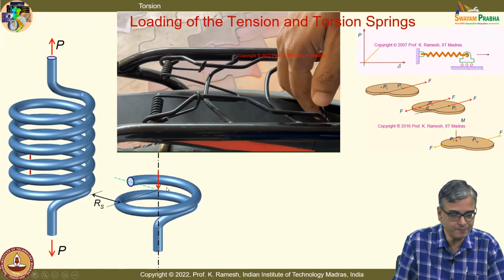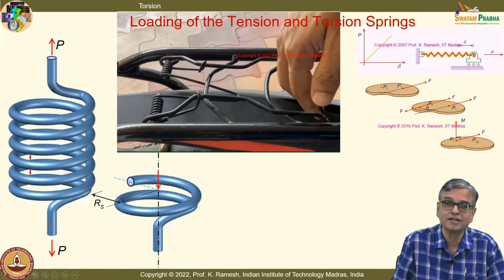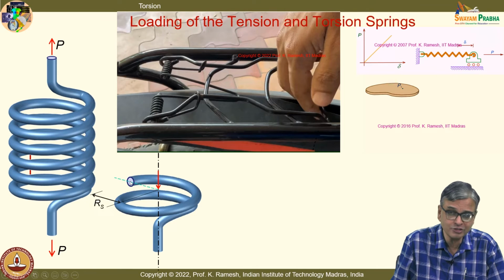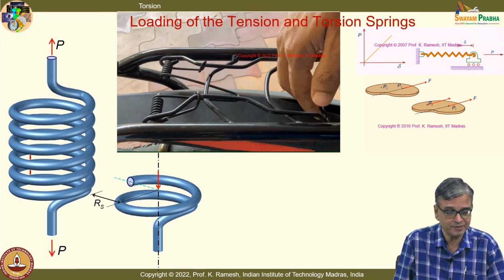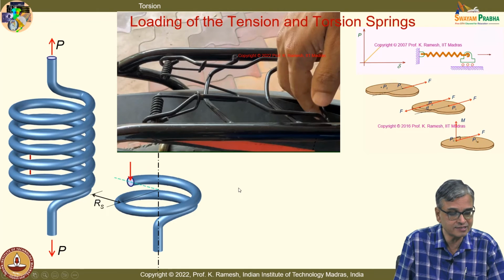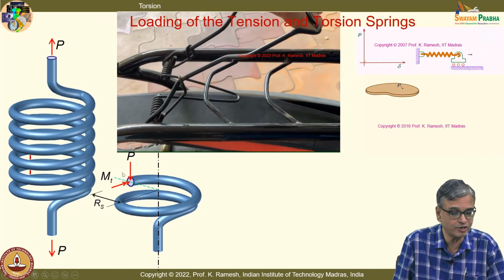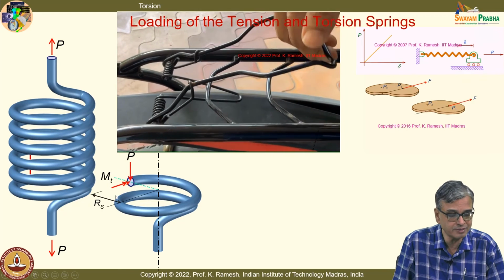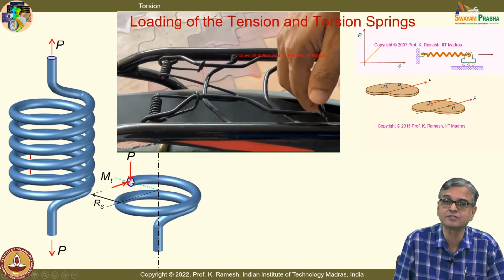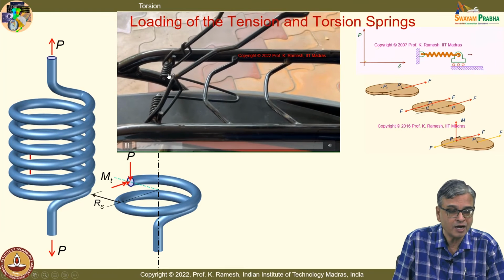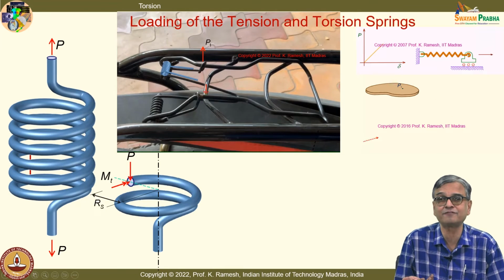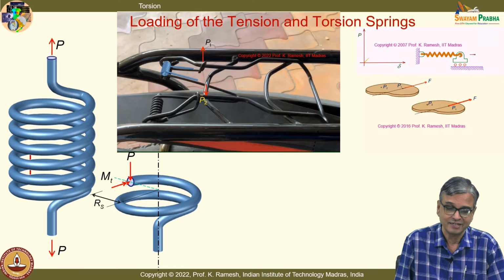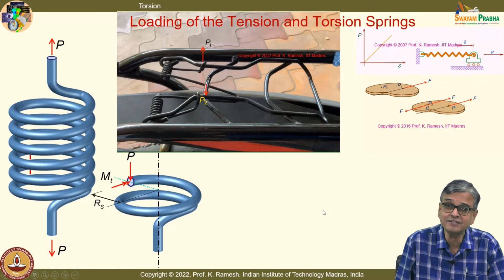But if I move from this axis to this, I will have a force as well as an appropriate couple. Here you are getting this couple in such a manner that it is along the axis, so it is a twisting moment. So, I will have a twisting moment as well as a shear force. Then we moved on to how to analyze the torsional spring. You say torsional spring, but what is the major force it is transmitting? Its major force transmitting is bending.